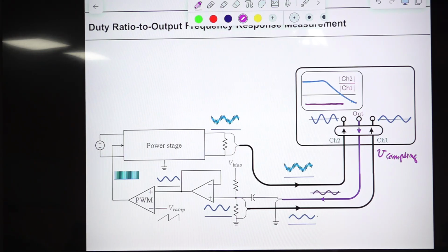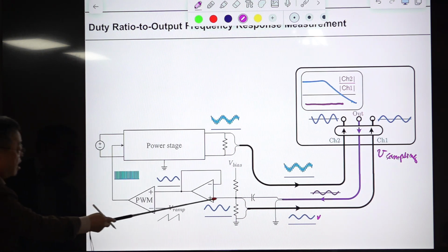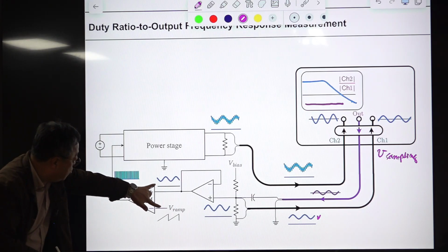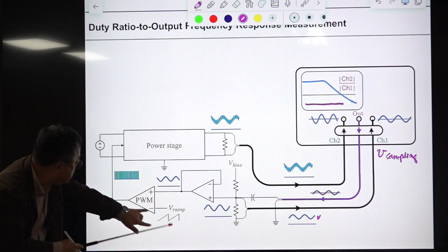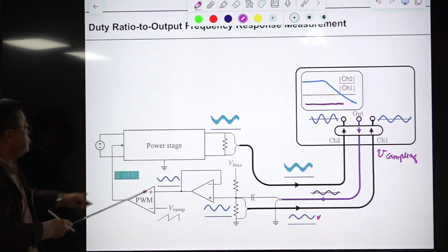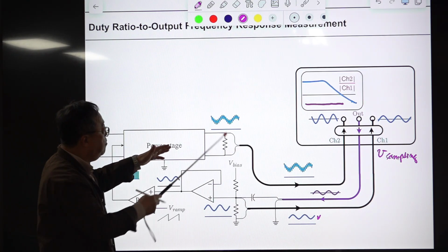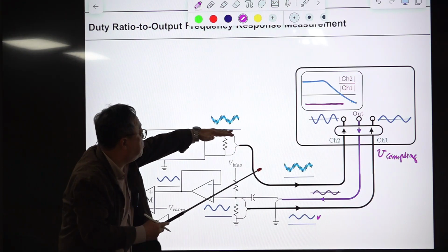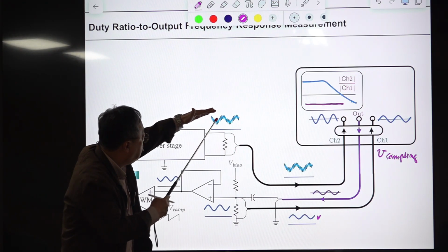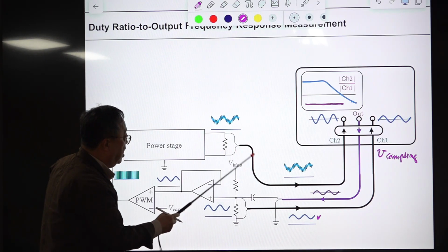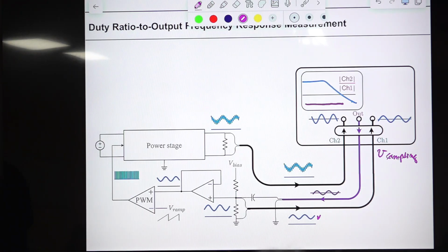Extracting this input signal, and that signal is also passing through this, and it does the PWM with this, and generates this sinusoidally modulated switch drive signal, and this signal will generate this waveform, and the output waveform has a DC value, and it has some ripple component and the AC component corresponding to this frequency, and it extracts the output voltage. VS sampling and VO extraction.